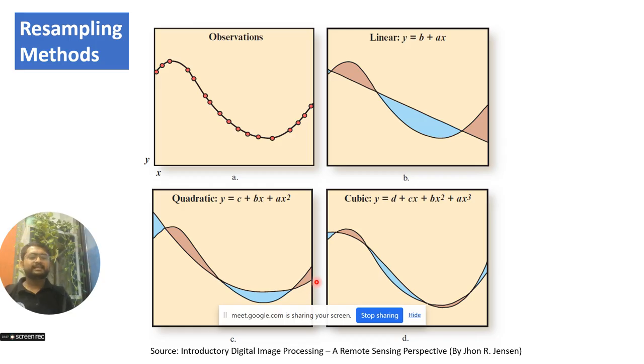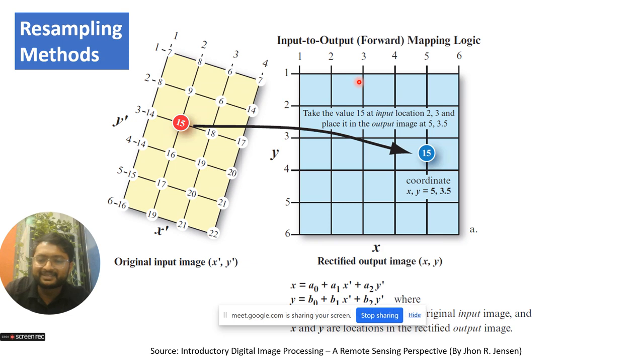So the basic idea is you apply a function depending on knowing the geography of the region, and then you also find the RMSE where you have actual points. So basically, if I tell you to find the RMSE here, I already know these points, the x and y coordinates of all the points denoted here. So I will take around 70% of points to fit the curve, and 30% of points I will use to see what is the error in my data set, and through which I will find the best fitted function for the resampling method.